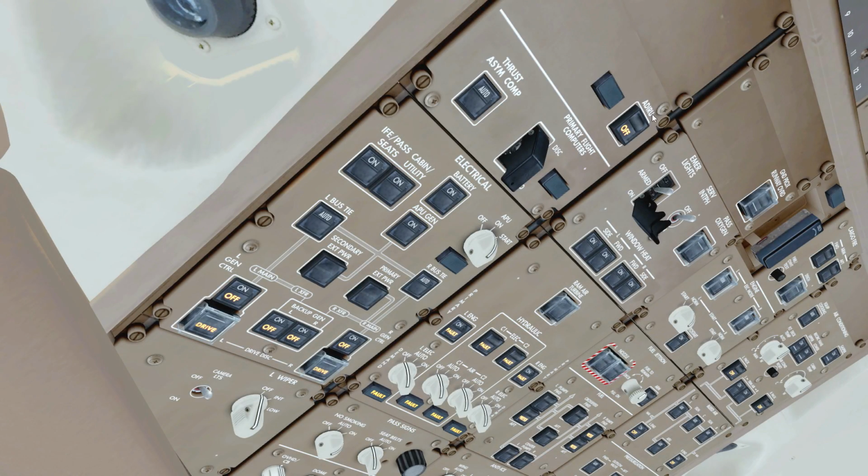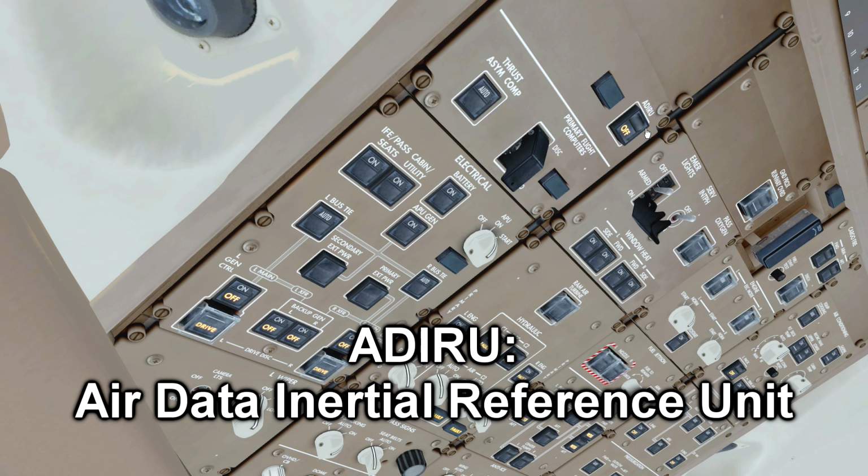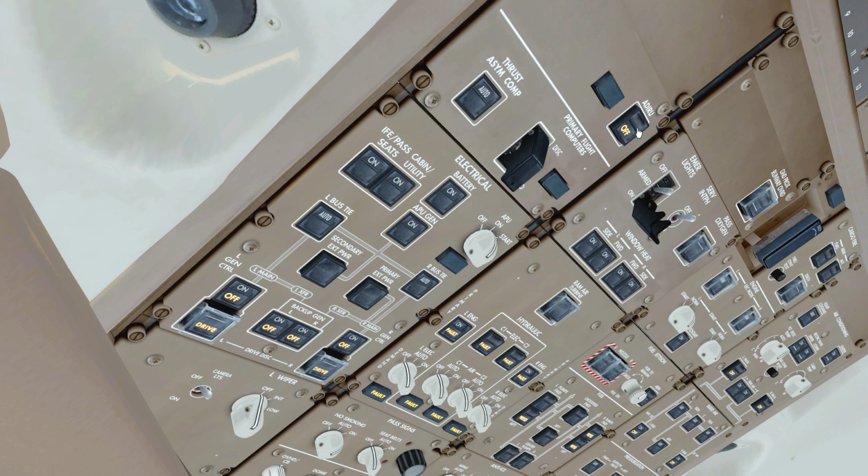First we have the ADIRU, which stands for Air Data and Inertial Reference Unit, and basically this is kind of like the IRS that you would find in the 737. So this system consists of the air data units, which helps calculate things like airspeed and altitude at high altitudes, and the inertial reference units, which allow the aircraft to determine its position in space. And again, we have to align that, using the latest GPS coordinates, to make sure that the aircraft knows where it is in space. So we'll just turn it on right here.